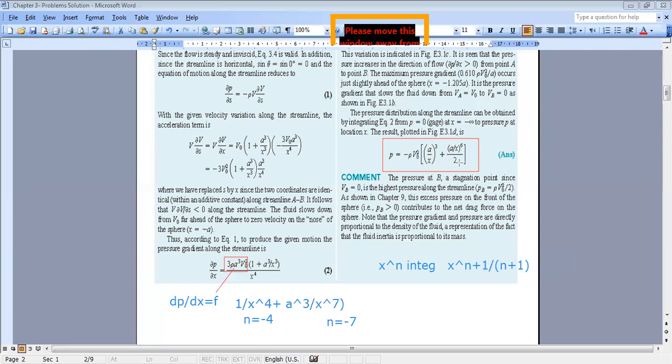If you want to verify your relation, okay, we can replace back by the two boundaries we have already worked on together. We said that at x equal infinity, p should be 0. And you can verify here that if you replace x by infinity, this will be 0, and also this will be 0. Now, we already calculated together p at b, okay? We have demonstrated from Bernoulli that p at b is 0.5 times rho times v0 square.